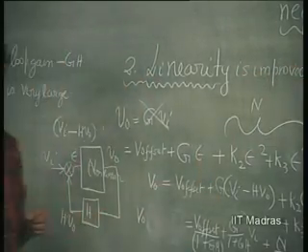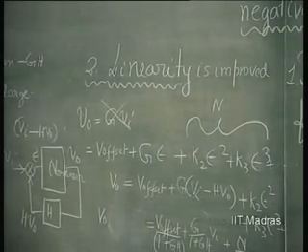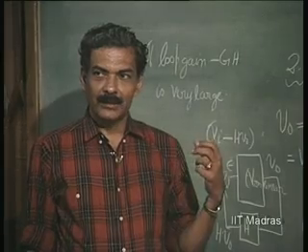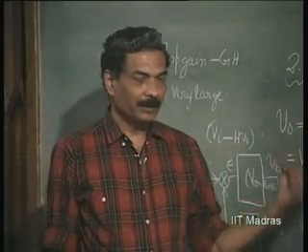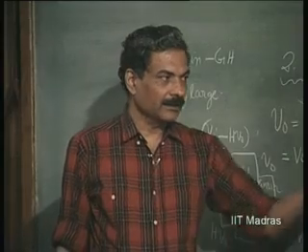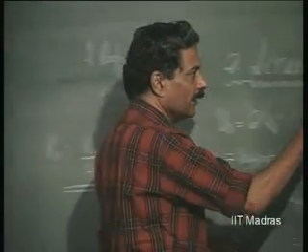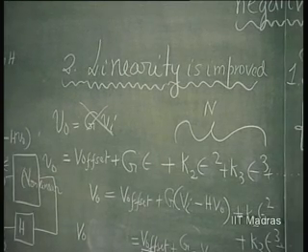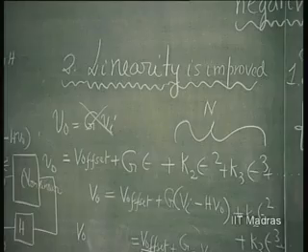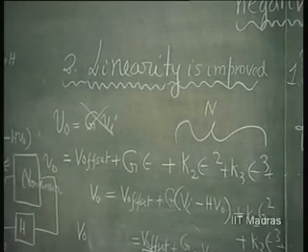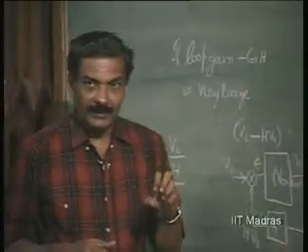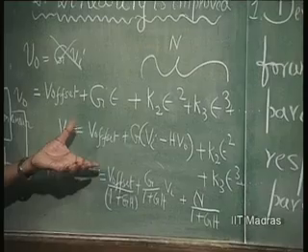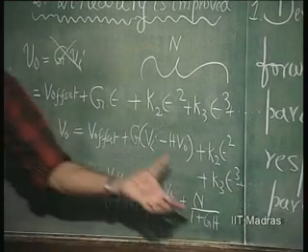And you will note that any improvement occurs by a factor of 1 plus GH, that means the loop gain factor comes into picture in every improvement that occurs in all these things. So, this is the second important conclusion that we arrive at, saying that in any negative feedback system, the amplifier forward transfer parameter is desensitized with respect to variation in active parameters, number 1. Then it is also going to have low amount of offset voltage and nonlinearity associated with it.